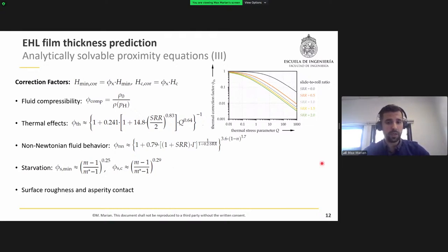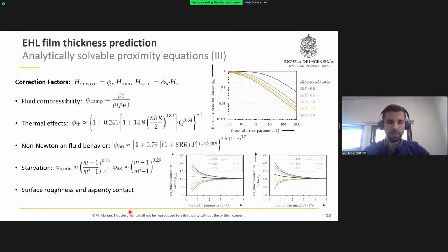Yeah, and finally, it is well accepted that the surface topography, in terms of any kind of stochastic deviations from the smooth surface due to manufacturing, or also intentionally produced surface features such as surface textures or structures, has a decisive impact on the film formation in EHL contacts. And with decreasing lubricant film thickness, the impact of the surface roughness is getting stronger on the pressure buildup and also on the film thickness